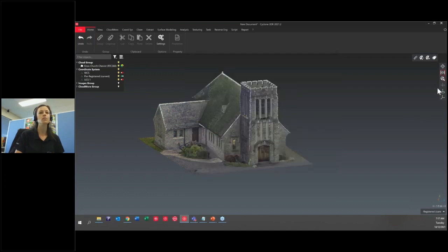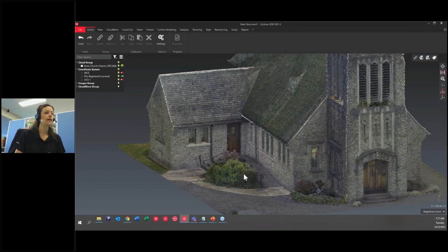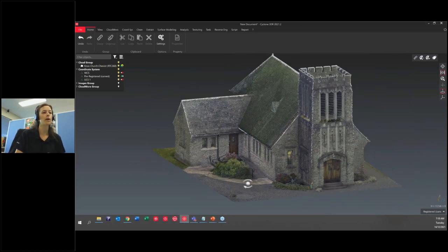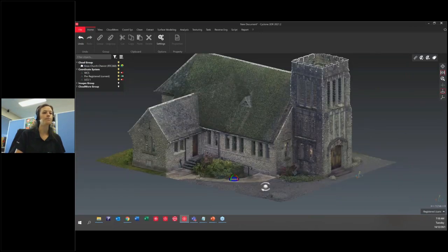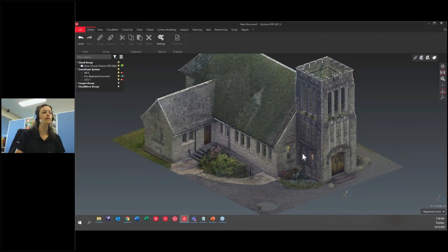Little tip there. There's one option that's extra when you use the 3D Reshaper way, which is that little tool there to keep your data vertical. When you're using the other way, the Cyclone 3DR way, you don't need that because it's done automatically for you. So potentially it should be easier actually. Here we go. So now that we're in here, the main thing before starting to mesh something is to understand what we would like to mesh and what we would like to get out of the mesh data really. So in this case, we chose to work on a beautiful example and show how fine the mesh can become so that we can really show detailed meshing on something like this. So we really want to have as much detail as we want here, and so on.